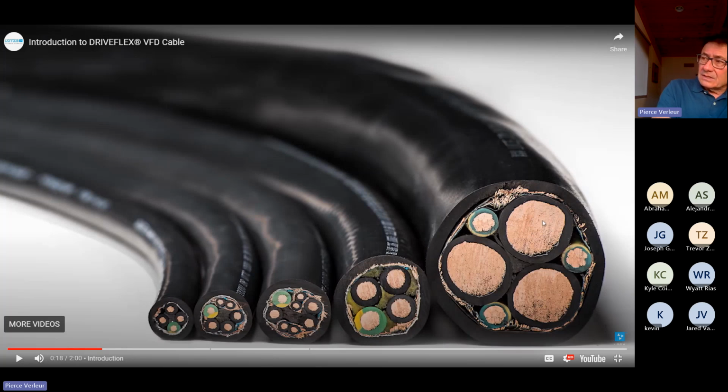So, this geometric configuration causes additional cancellation of this noise because of the geometry. Therefore, this is, from a noise standpoint, superior to this. This also allows the cable to be a smaller diameter and thus more flexible. So in the installation and cost of handling standpoint, it is superior.